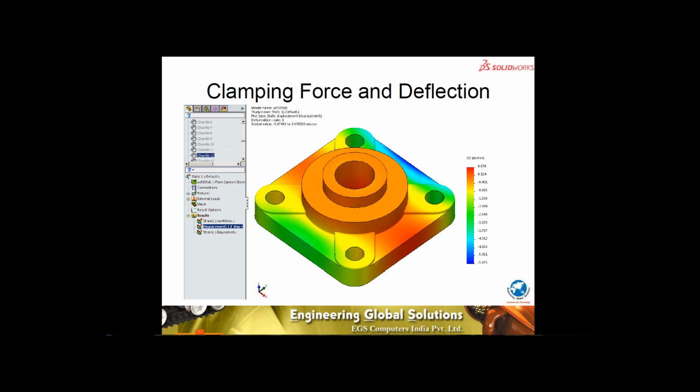Now, if we do not provide enough support surfaces on the datums or the locating pads, or the stiffness of the component is inadequate with regard to the tooling forces that come during entry and egress of the tool, then we have deflections coming into the part as the machining operations take place, and once the clamping loads have been removed, the part loses its flatness. These can be studied using a simple single touch tool to look at the clamping force adequacy and their effects on the deflection on the part.